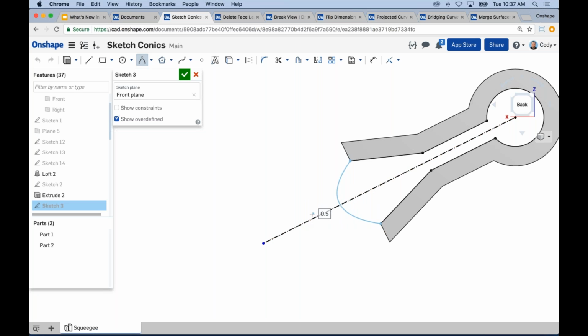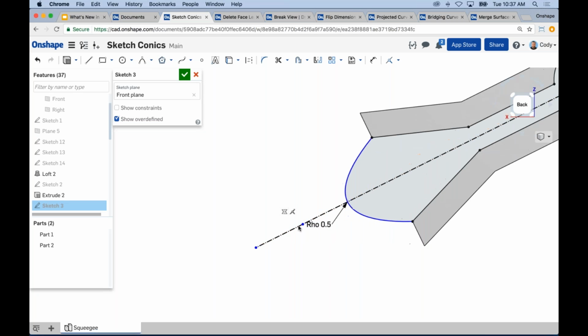And I can do a few things with this. I can attach the point here, right? And when I left click, I can enter a rho value, right? So let's say 0.5. Now, you also have a point that you can manipulate. So if you decide to attach this point to another endpoint, for example, and then dimension that, whatever it may be, just keep in mind you have a point out here that allows you to attach and give you things like symmetry, like in this example.